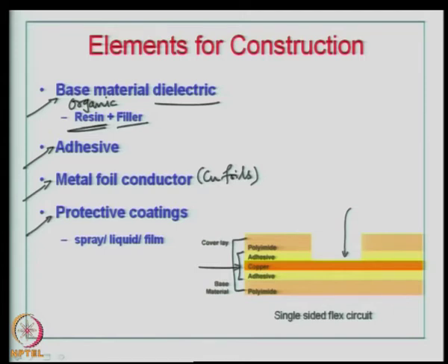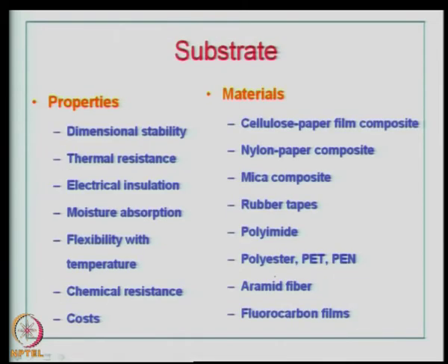Essentially, flex circuits are looked at as a connector to connector connection or a point to point connection, rather than having a complex circuitry built on the entire body of the flex base. So, you can have the conductor lines. The copper represents the conductor lines that are defined by the design, the length and the width and so on. Single sided flex circuitry will have this kind of construction. The copper is protected by the polyimide dielectric and the adhesive material.